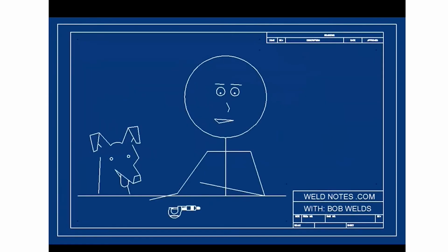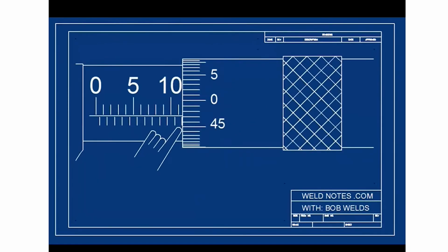Okay, there's just one more small concept and we'll be done. What if one of the marks is just barely showing? Do you count it? Is it ready to be used? Here is the trick. Don't look at the mark to find out whether the mark is showing or not. Look at the thimble. You need to know if a new mark is starting or if an old mark is ending.